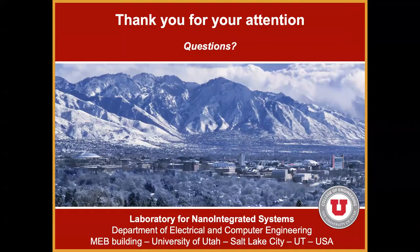So one question, and the students maybe are thinking something. If I were going to extend to a CGRA kind of thing, so you have the FPGA frame, but then you start to add more coarse grain things, I guess I will have to have a new tech map step. Which one are you using for the tech map? And I'm not so sure if the VPR will be able to handle it. What are the things I will have to change in order to get something like that working in the flow?